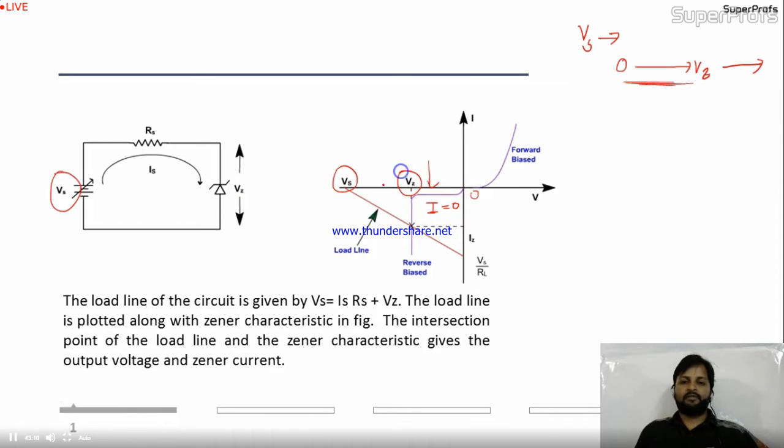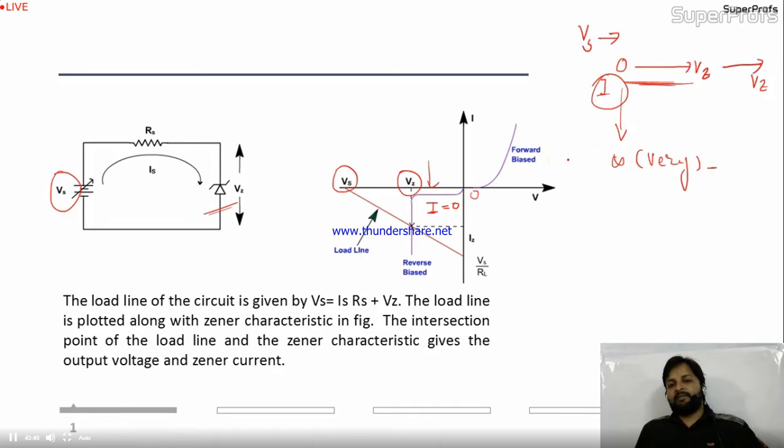After breakdown, once the voltage across the Zener is raised to VZ value, it's going to break down. When it breaks down, the depletion layer breaks and you are getting a tremendous amount of electrons. So you'll be having very high current. Now the voltage after this stage is not going to change. Voltage will be that much only, but your current is going to infinity, meaning very high current, but this current will be decided by the circuit parameters, in which circuit you have connected the VZ. Okay. So this is all about the Zener waveform and characteristics.